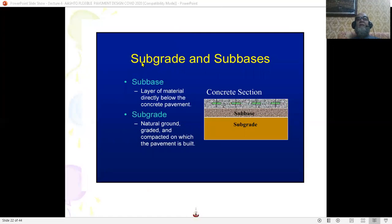Now, the subgrade and subbases. Remember, here subbase is the same as base in asphalt concrete pavement. What is happening here is that the rigid pavement slab, this concrete slab, is resting on the subbase. You can call it subbase, or you can call it crushed aggregate base course. It doesn't make any difference.